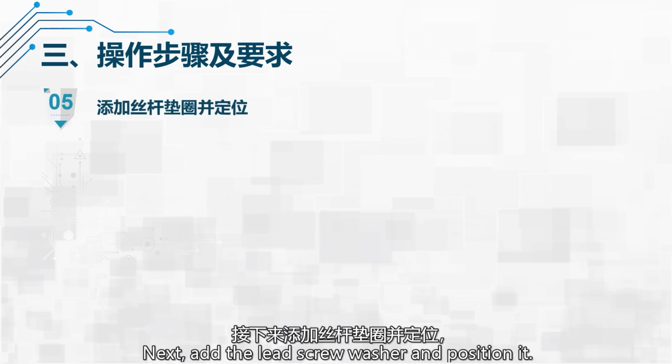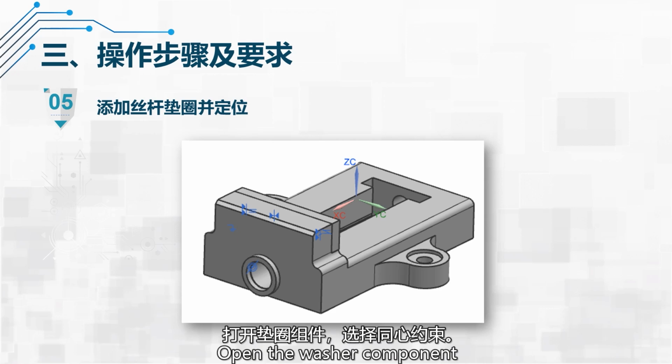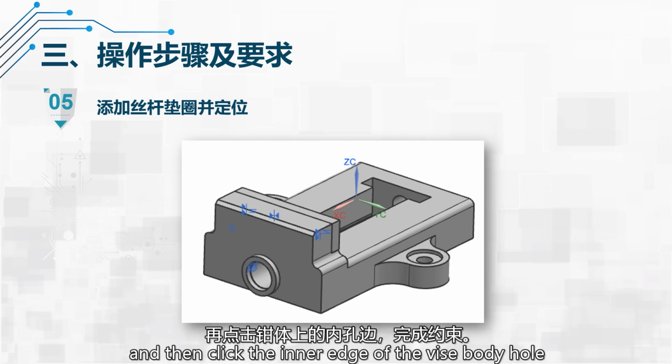Next, add the lead screw washer and position it. Open the washer component and choose Concentric Constraint. First, click the inner edge of the washer hole, and then click the inner edge of the Vise body hole to complete the constraint.